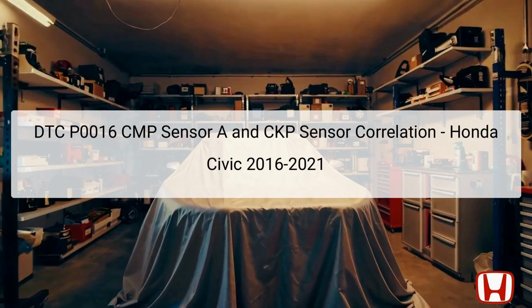The CMP sensor A is typically located near the intake camshaft, and the CKP sensor can usually be found near the crankshaft. If these sensors do not report accurate positions, the engine control module, ECM, cannot optimize fuel injection and ignition timing, leading to engine performance issues. Before addressing the issue directly, it's essential to clear existing diagnostic trouble codes, DTCs, and ensure no other related codes exist. The troubleshooting process should also check for intermittent failures by examining sensor connections and wiring.